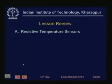So we have come to the end of this lesson. Before we close, we need to review it. So we have looked at temperature measurements briefly, of course, and we have looked in some depth at resistive temperature sensors of two kinds. Firstly, we have looked at RTDs, which operate over longer ranges, are very stable and give rise to accurate instruments, but their sensitivity is not that high.